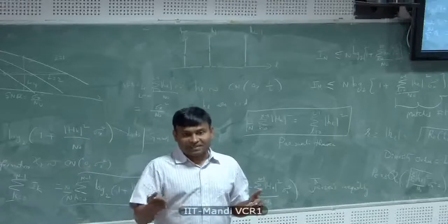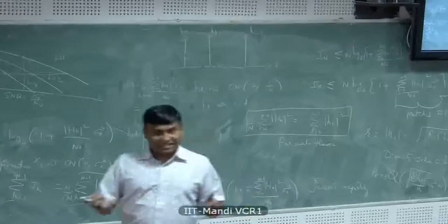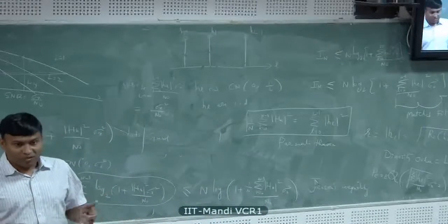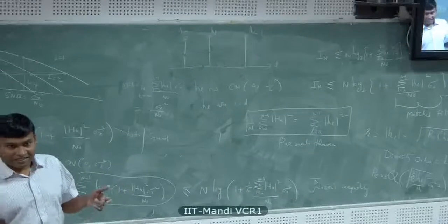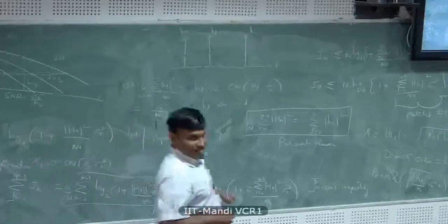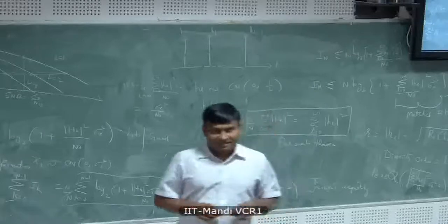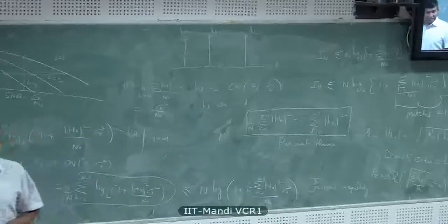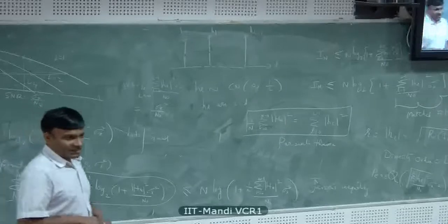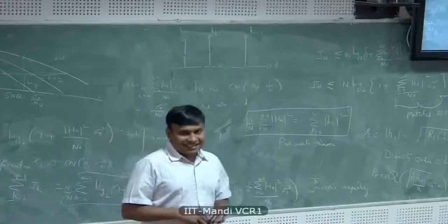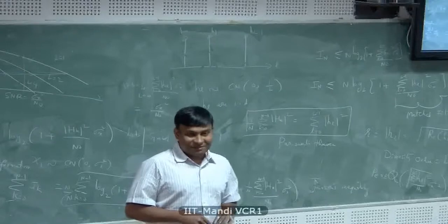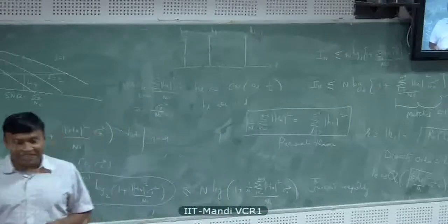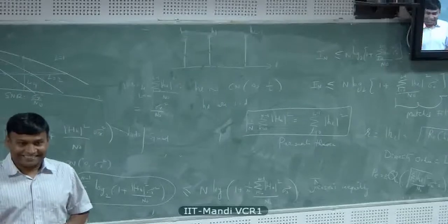Well, it depends on the carrier frequency, right? If it is 800 megahertz, what is the spacing required? It's on the order of 30 centimeters. 0.3 meters. Yeah, that's quite large. You need an iPad-like device to give you 30 centimeters. So that's why GSM phones don't have 2 antennas.